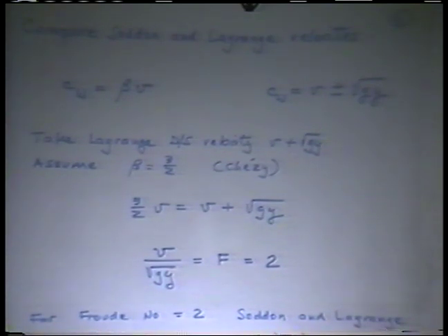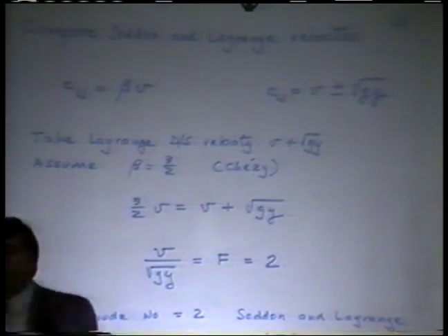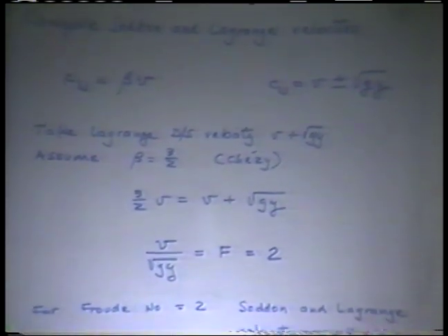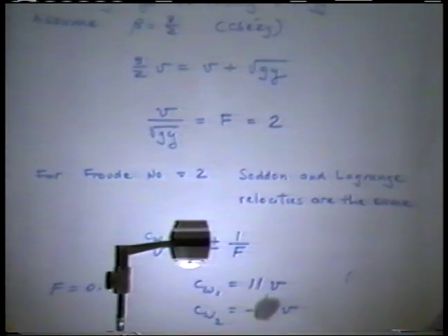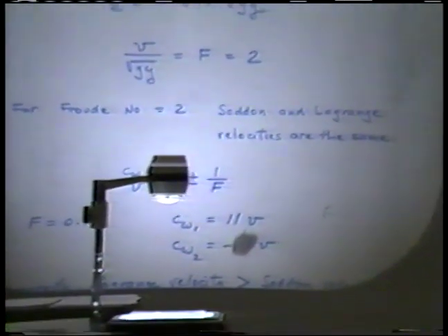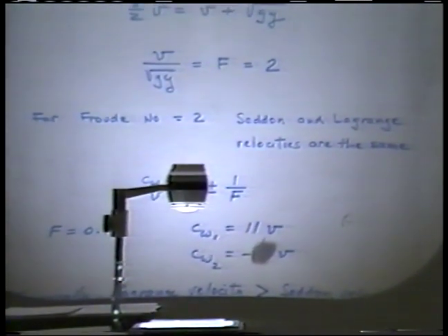Now let's explore for a moment, what does the literature say about the condition of Froude number being equal to 2? You can go back to the work of Dressler, the work of Lighthill and Whitham, and others that have shown that for Froude number equal 2, there is flow instability on the surface. And in fact, these are the so-called roll waves that Chow, as well as many others, have described.